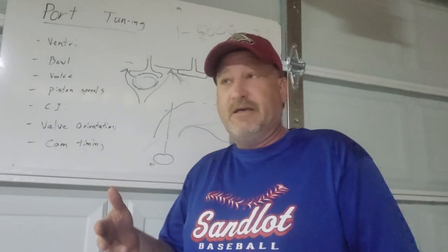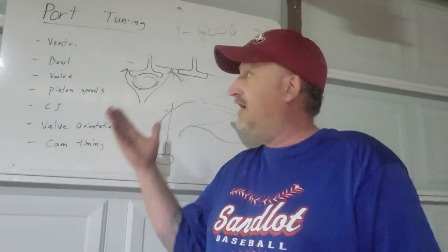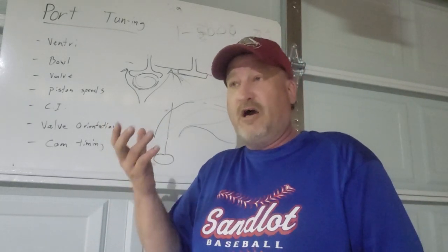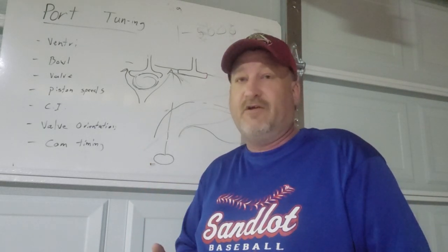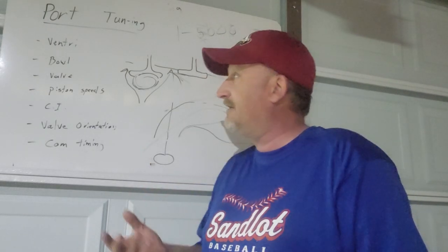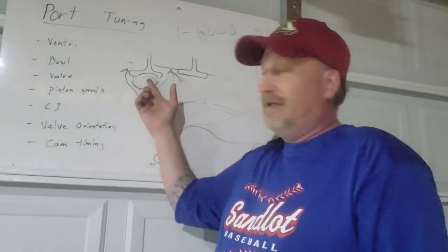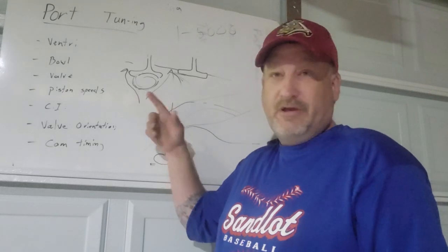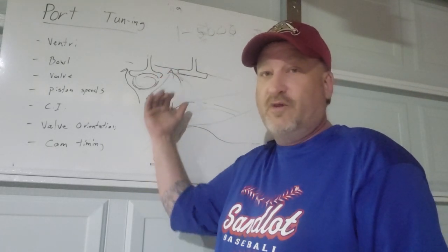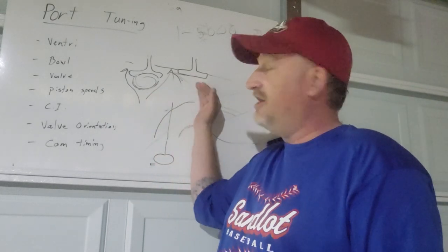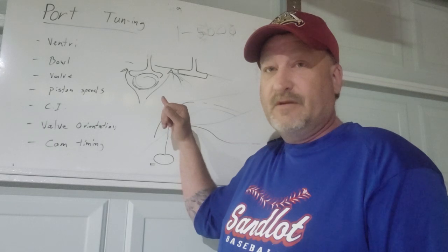If you change connecting rod length, it's also going to alter the piston speeds of when it is actually creating, or how aggressive it's creating the vacuum within the 50% travel of the piston itself within the cylinder. The valves, once again, it occurs in both directions, not only when the valve is open, but what is the air doing when the valve is closed? Is it initiating airflow from one side of the cylinder to the other?